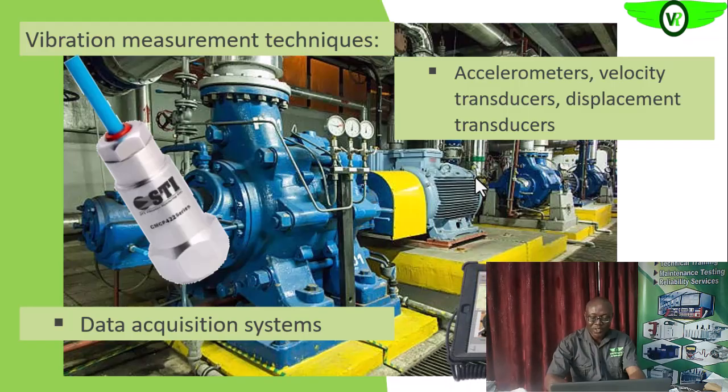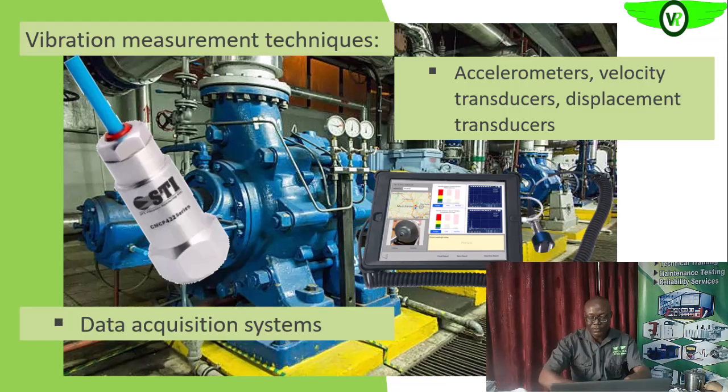information from. So this is your vibration analyzer. And this is the vibration probe, or transducer, which could be an accelerometer that you place. The base is magnetic, so as you place it on the bearing housing, it magnetizes the housing and gets attached itself to the housing on the particular spot or direction that you placed it.